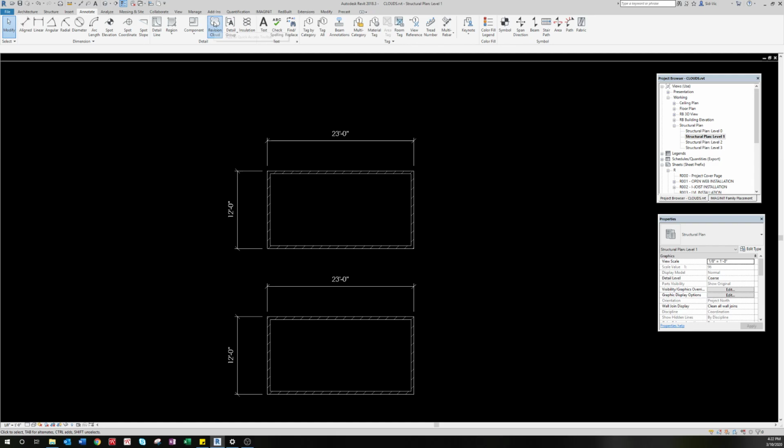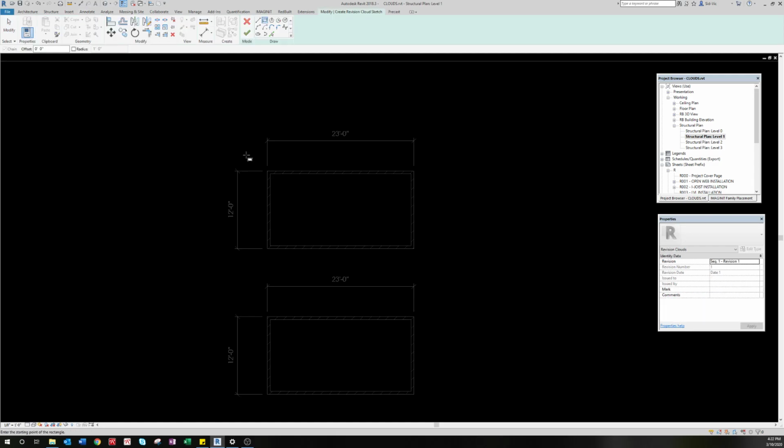Once you initiate this, you're going to notice that your screen turns a different color. And again, as I've always found with Revit, when we're working in a command, once you activate it, pay special attention to your Modify tab, where you're at. You're in a modify setup. What is your options bar asking or telling you, and what is your properties box containing inside of here?